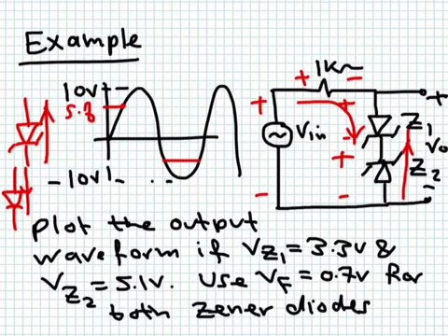Where does the rest of the voltage go in the negative cycle? Well, there is a current flowing in this direction, and this current causes a drop of plus and minus across this resistance here, and the resistance will absorb the rest of the voltage drop. So the current will be adjusted. This current here will be adjusted at every time in order to make this resistance absorb the rest of the drop.